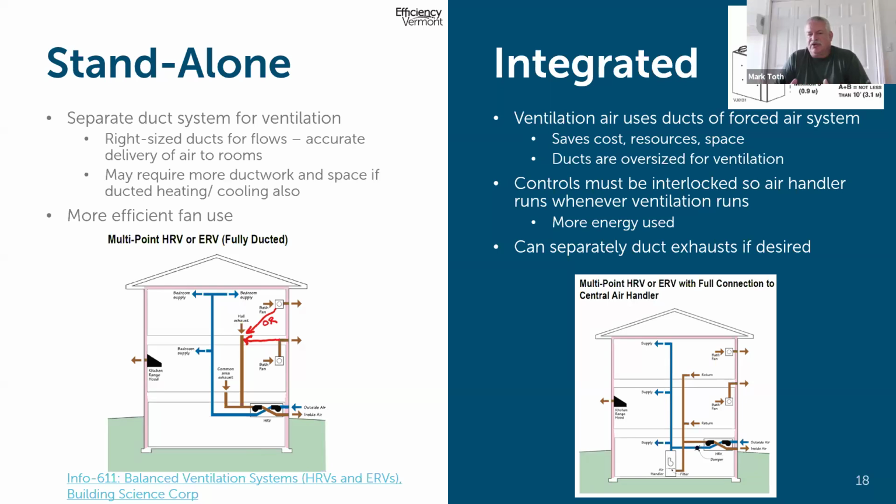But if you're building a house and you're going to use ducted heat pumps or maybe a Unico high velocity or any type of ducted system, the other opinion is if you have ductwork there already, why duplicate the ductwork? There's multiple reasons why not to duplicate the ductwork. There's the cost of duplicating ductwork, of materials and labor. There's the environmental cost of duplicating it, that you're using twice as much material. You're going to have a lack of space because you're going to use twice as much space than you needed to. So there's a lot of reasons why not to do it.